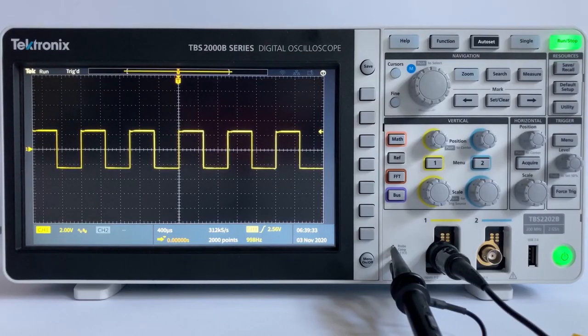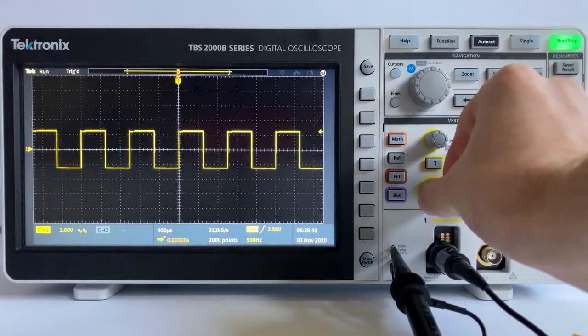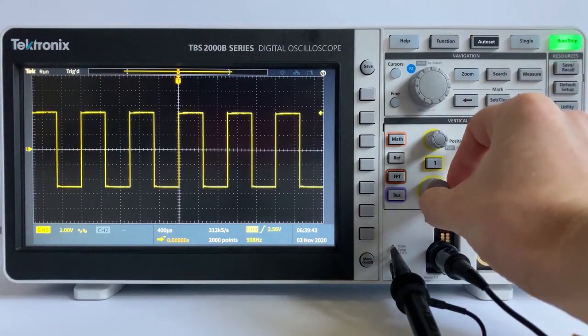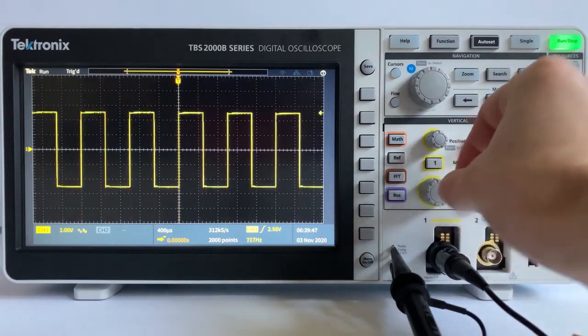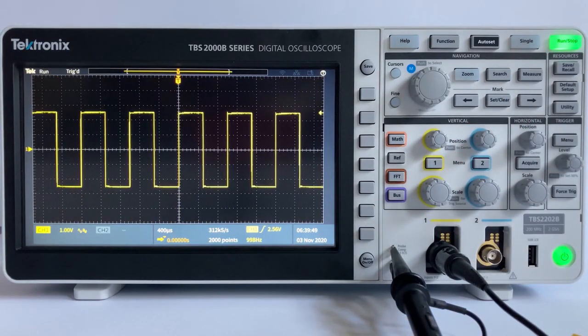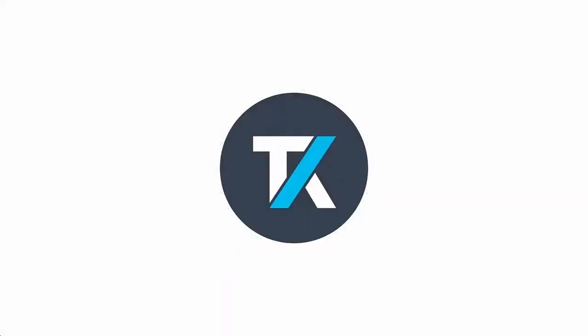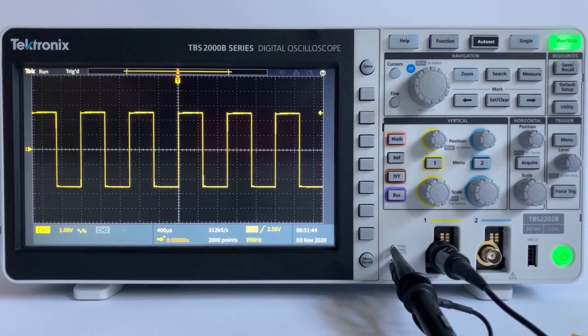It should be noted that the top and bottom 3 quantization levels are typically reserved to indicate and detect signal clipping. To get the best signal resolution, use the most sensitive vertical scaling setting while keeping the full waveform on the display. If the waveform is scaled to consume almost the full vertical display, then you are making full use of your oscilloscope's ADC. The vertical settings control the Y or amplitude axis.